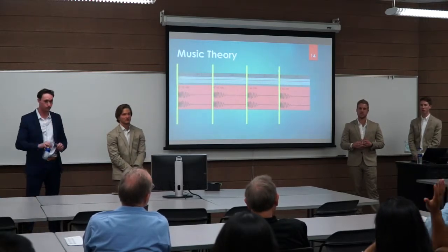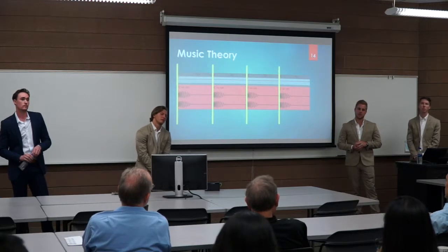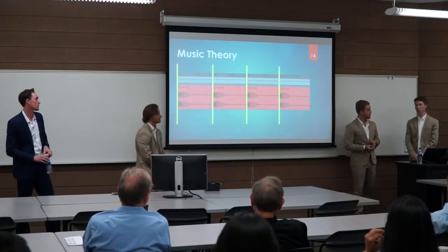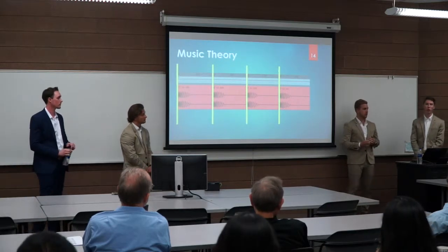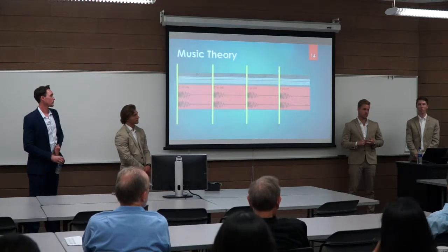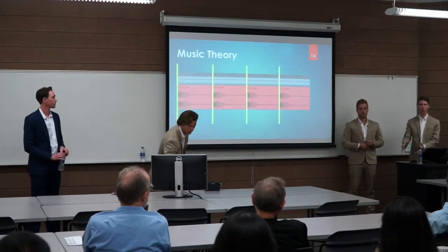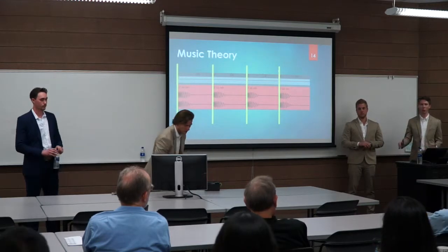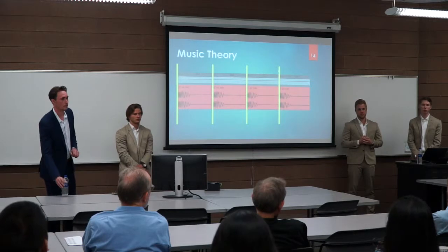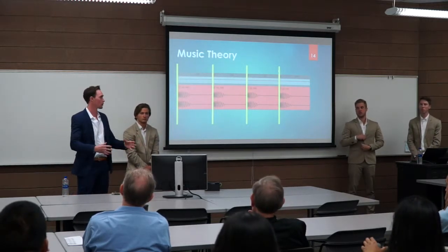Okay. Yes, ma'am. Did you do any testing to see if you guys would pick up any noise from like a bass frequency, like bass guitar? So that was one issue that we thought we might run into, but it totally depends on how close the actual bass is to our system. If the bass is putting out a dB level relative to Thunder Buddy lower than whatever the kick drum is, it won't activate our gate and it won't affect it. Okay. And because that is a mechanical sensor, we do get some isolation just by physical proximity.